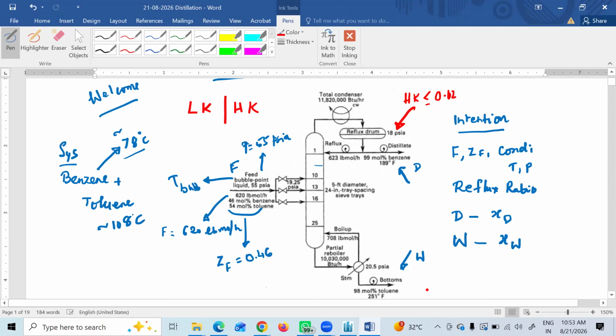And in the bottom product, the light key. Generally in the specifications of the simulation columns, you should understand this terminology. For light key, you need to mention whether it is less than 1%, less than 2%, or less than 5%, depending upon the requirement. So this is the problem description as of now.